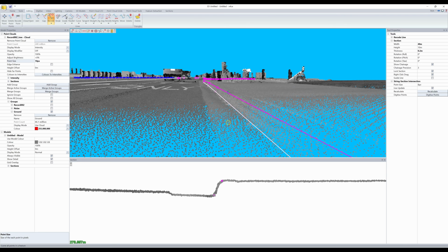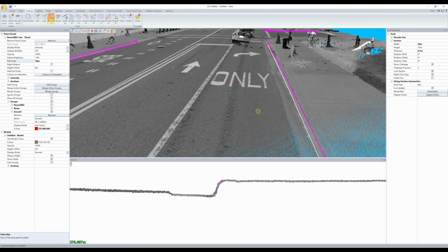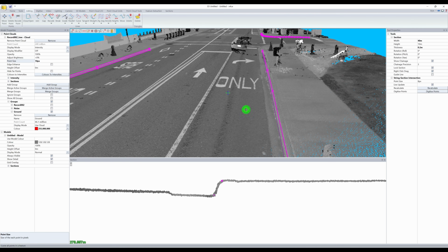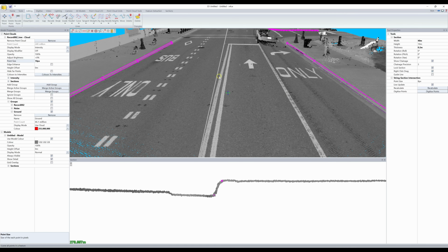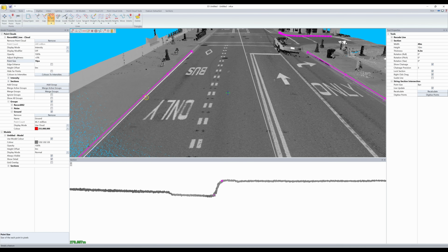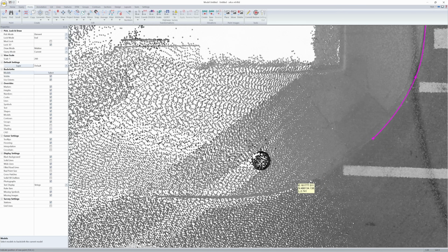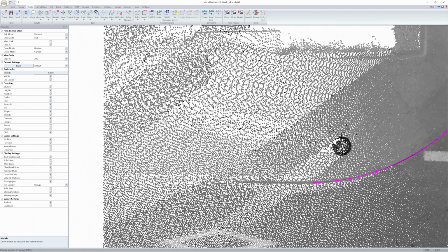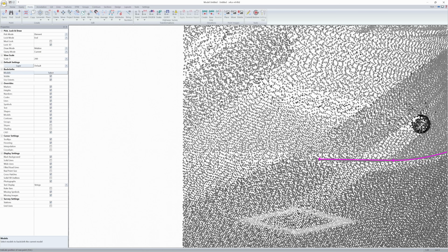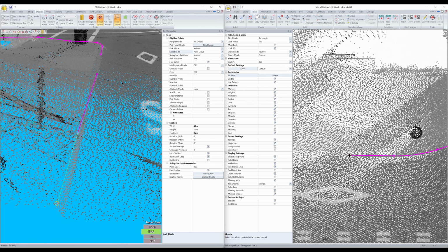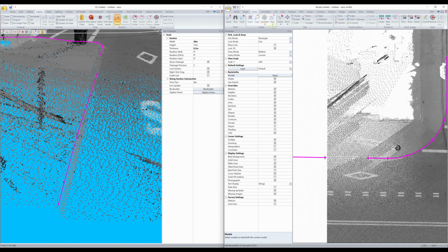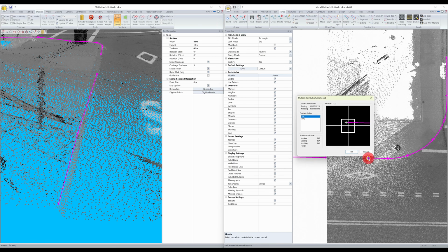Now, while this isn't as fast as digitizing on an ortho, it's significantly more accurate. The key to efficiency and quality in N4ce is to mix and match techniques to best fit your data and your desired accuracy. If you're working your way along in the model view and come to a part of the data where some features are hard to pick out in 2D, ideally the 3D is open on your other screen and you can immediately switch over to picking them out in there.